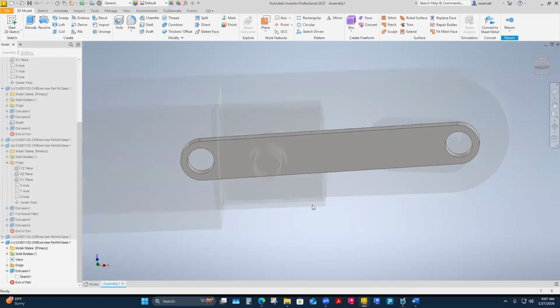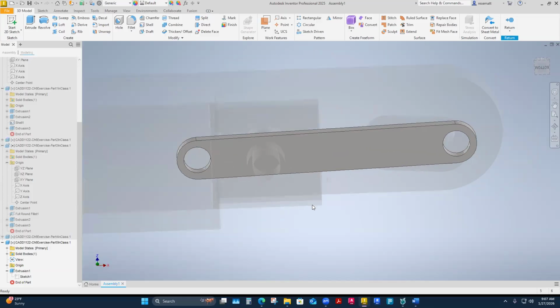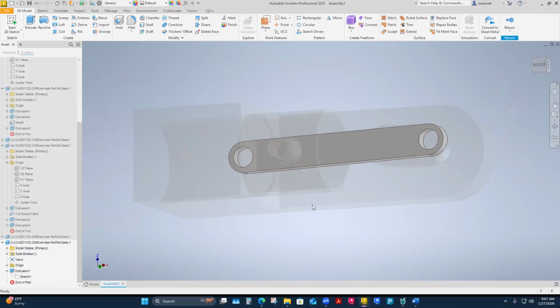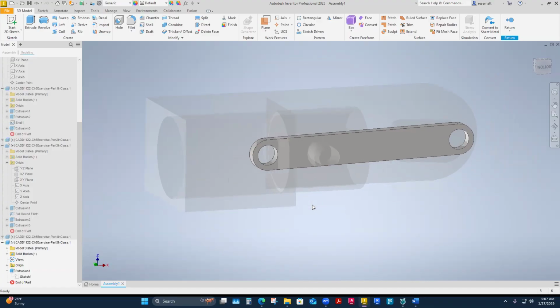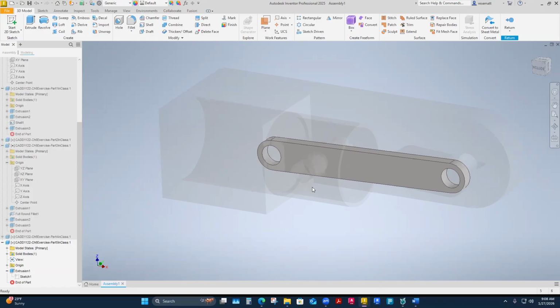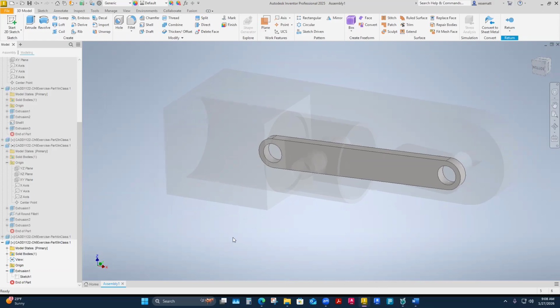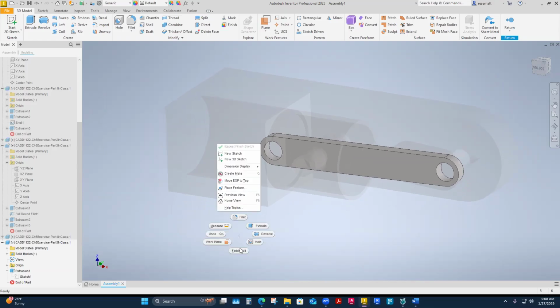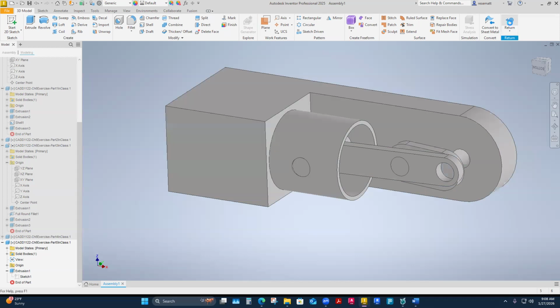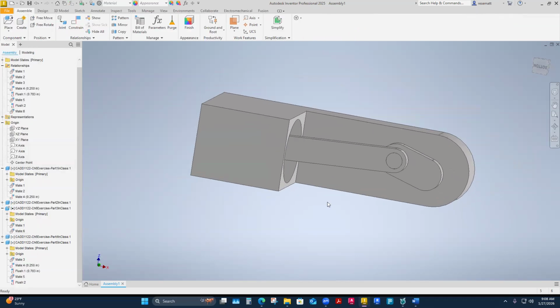Yeah, I just finished my sketch. Yep, I just did my one data input, finished my sketch, bam, it just kind of blew up. Change, and then I'm still within the edit mode. So I think you can right click and say finish edit, or up here on this return is like return to the assembly here. And I think it closes down the edit mode here. So either one, you can right click and finish, or you can say return up here, and then it's going to make those jumps.